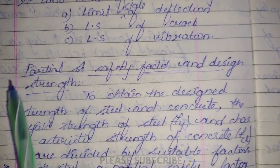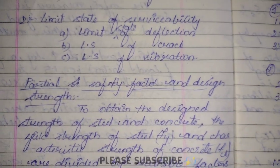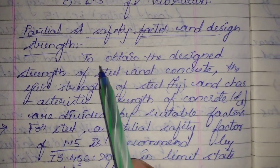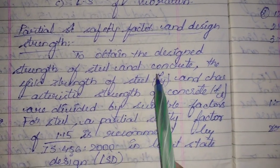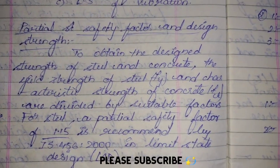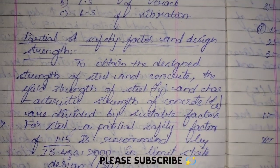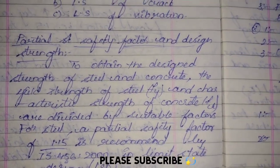In this we are not having the load factor, wherein in the ultimate method we were getting the ultimate load by multiplying the working load with some factor called load factor, that is 1.5. Here we will be having the partial safety factors and the design strength. Okay, so to obtain the design strength of steel and concrete, the yield strength of the steel, that is Fy. So remember, whenever we are saying Fy, that is the yield strength. Okay, and the characteristic strength of concrete, that is FCK, are divided by the suitable factors. So here we are dividing. Okay, in that case we were multiplying to get the ultimate load.